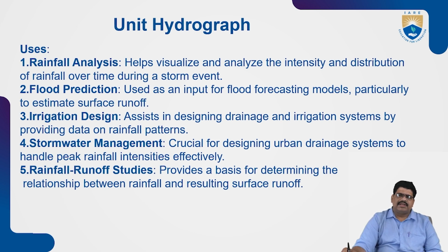So, why do we have to calculate the runoff? Because on a particular catchment area, we need to know how much water will come according to the rainfall intensity and rainfall data. For any construction of a hydraulic structure, the calculation of the runoff is very important. During the analysis only, we decide which type of structure has to be constructed. That is very, very important.